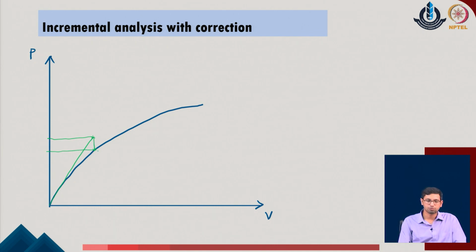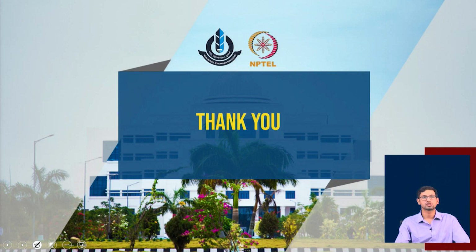Once I am able to correct this value, I will try to come down to the same position on the given curve. As I continue with the next value, I will further correct it and try to come to the given system, and this way we will have a procedure in which each increment of the system is also provided with a number of iterations such that the force values are not only taken as the final value at the beginning, but they are further corrected by using the simple equilibrium conditions to verify the results more accurately.